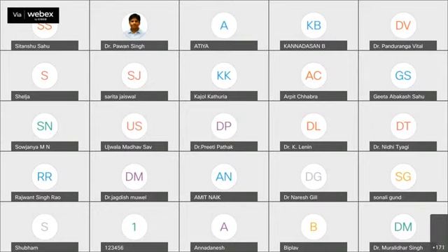If you look at its applicability, say this is a synthetic data, a waveform composed of low and high frequency. Let us look at what intrinsic modes, or oscillations, are present in the data sample itself. So we apply the EMD. First, we look at the local maxima and local minima in the input signal. The red dots represent the maxima, the maximum points in the variation of the waveform, and the blue ones are the minima.